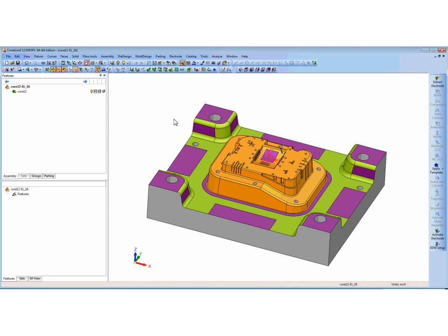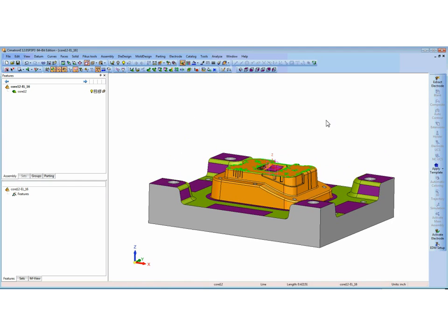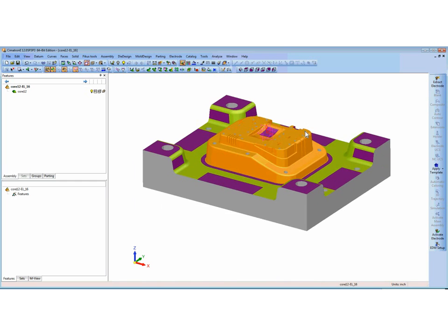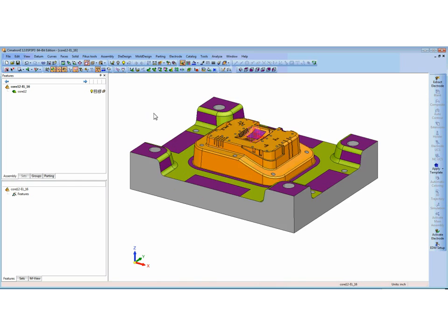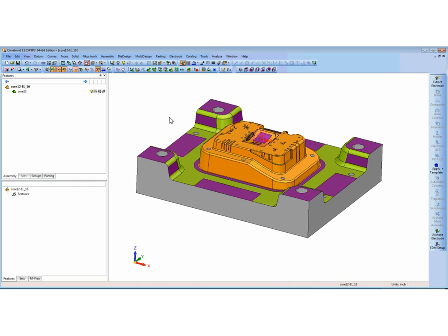And the first thing we want to care about is the coordinate system. We want the UCS, the user coordinate system, probably to be in the center of the block, maybe at the highest point. But sometimes the touch-off might be down here at the parting line. And I just want to quickly demonstrate how that can be done easily.